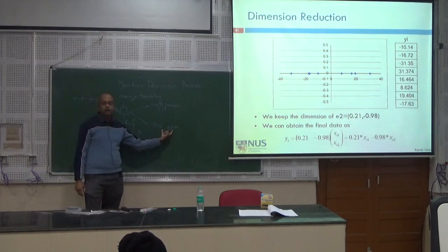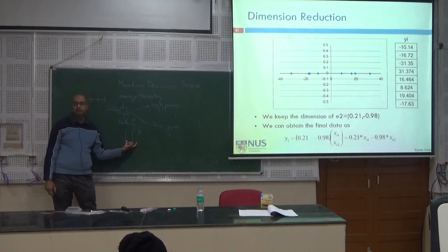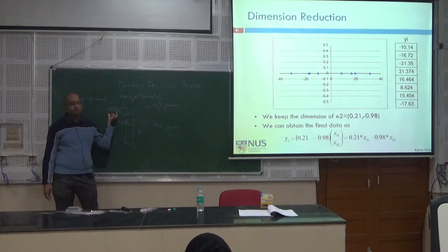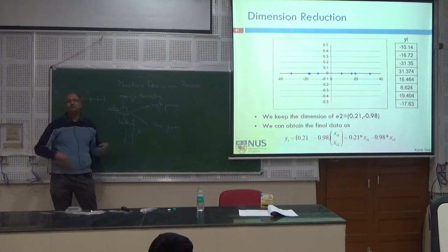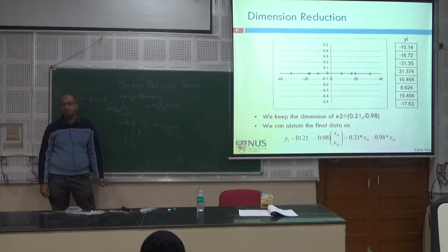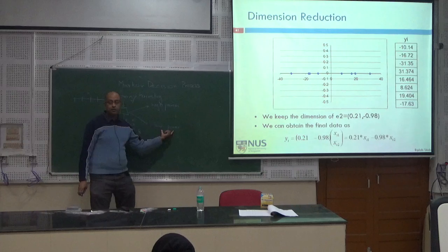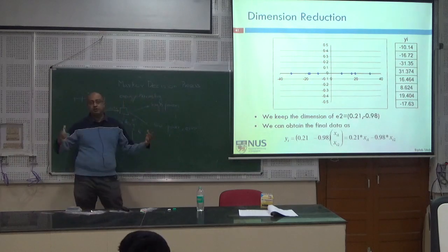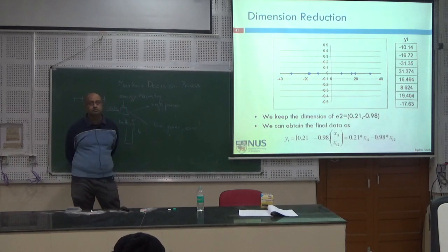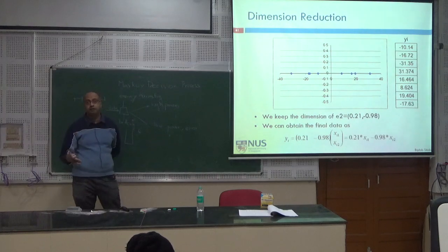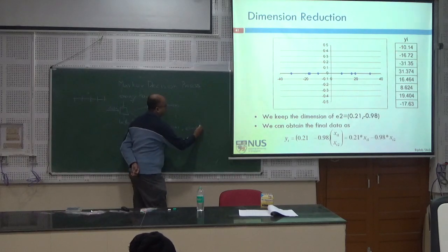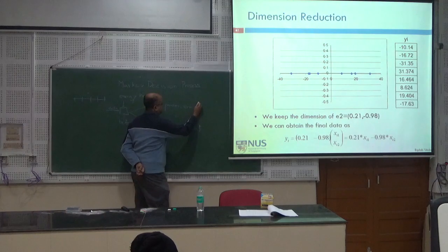If I transmit at low power, then I don't spend so much energy. So hopefully, cannot guarantee it, but hopefully if a packet comes in later, I still have some battery power left. It's more likely that I will have something in my battery left. So I would prefer this. But if I transmit at low power, it's more likely that I will have errors. My receiver will not be able to decode it. Depends on the signal to noise ratio, right? This means your signal to noise ratio will be lower because your signal power is low. So error is high. Error is low.